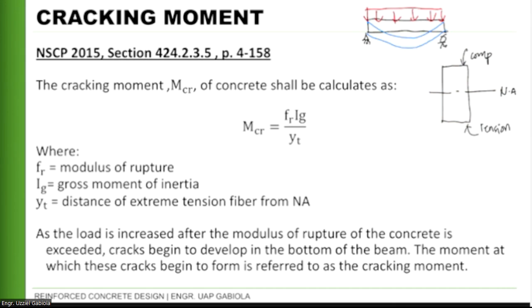And in reinforced concrete, we assume that at this portion we are reinforcing our concrete with rebars at this location. For the reinforcing bars to work, the tension side should already be in a cracked condition. That is why this portion is neglected, and we are just trying to look for the value of the moment that will produce cracking on that side.